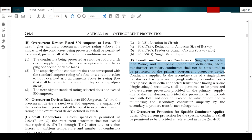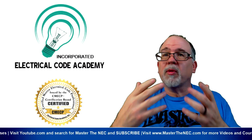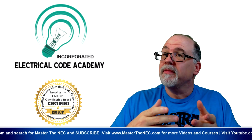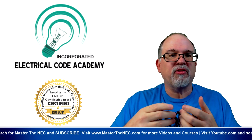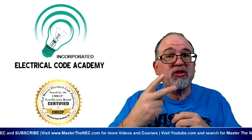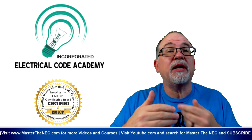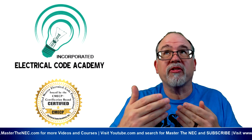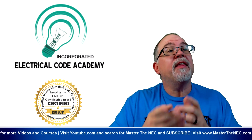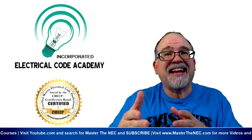What does that mean for us? Well, here's what it means. In all normal cases with all normal transformers, we're going to have primary and we're going to have secondary protection. However, if we're dealing with a single-phase transformer that has only a 2-wire secondary with one single voltage, meaning the secondary side is only generating one voltage, then the primary overcurrent protection theoretically can protect the secondary windings.